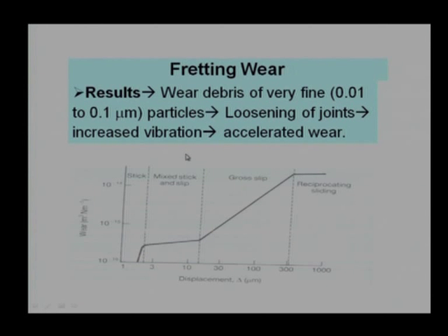Something like that: we bought a new component, a new assembly never used, lying on the table, or some assembly which was vibrating with a very small magnitude, and that vibration created a problem and the whole system collapsed because of fretting fatigue or fretting wear.